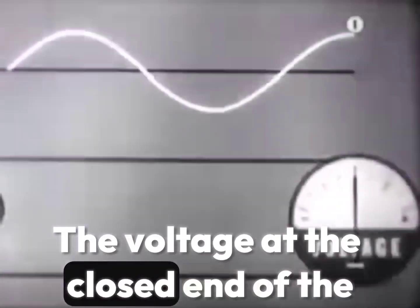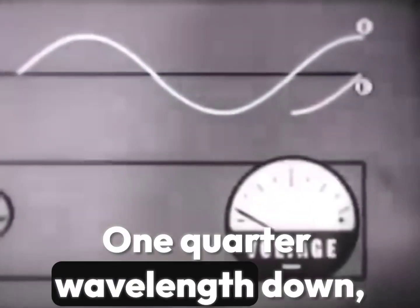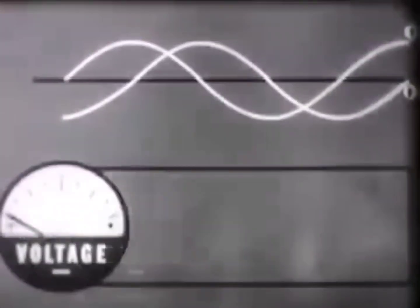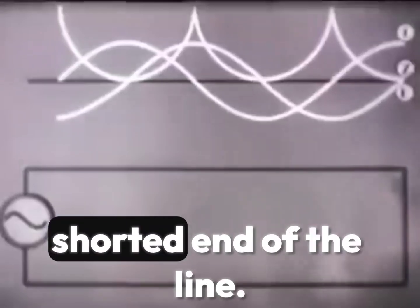The voltage at the closed end of the line is, of course, at minimum value. 1/4 wavelength down, the voltage reaches its peak, and so on to complete the standing wave of voltage. Impedance is minimum at the shorted end of the line.